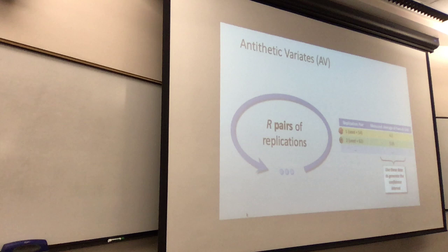And so these are washers that came out, and it turns out that due to how things were bolted together, this drum at high speed could actually launch out of the washer, and you can see there's a dent in the wall if you look at the slides online. And it would hit people in the head. People got major injuries from this effect, and it was just because there was a vibration slightly outside of spec as to what the latches on this lid could handle. And when you got into the random, this tiny little rare event, then you could pop this thing off and the drum could come flying out.